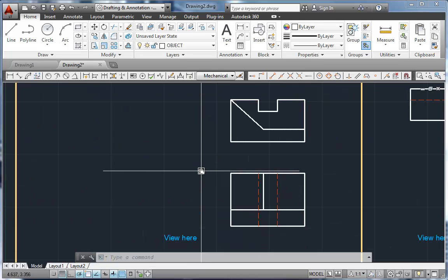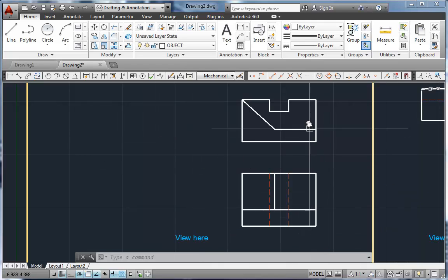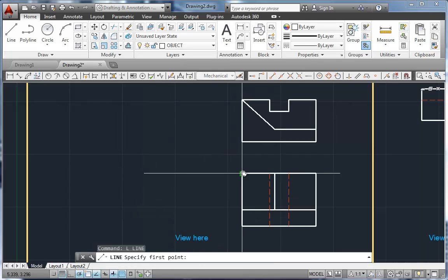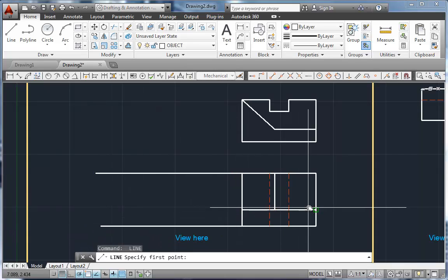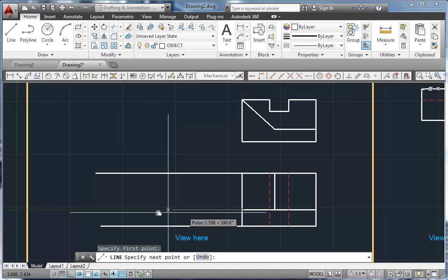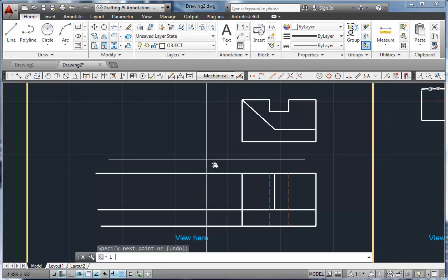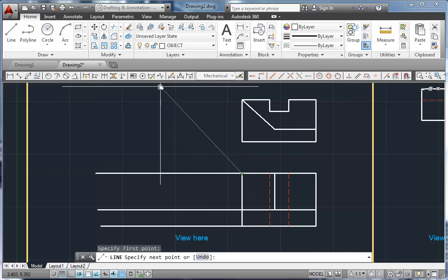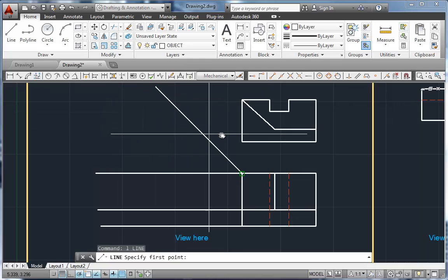And let's have a look at this one. All right. Interesting pair of views in terms of appearance. Again, we're looking for a left side view. I'm going to go ahead and transmit my height over. I have one more height here I'm going to have to deal with. I have a line here that looks to be probably a surface. So I'm just going to go ahead and transfer that also. I'll draw a miter line at an angle of 135. And then I'll transmit my depths over and around.